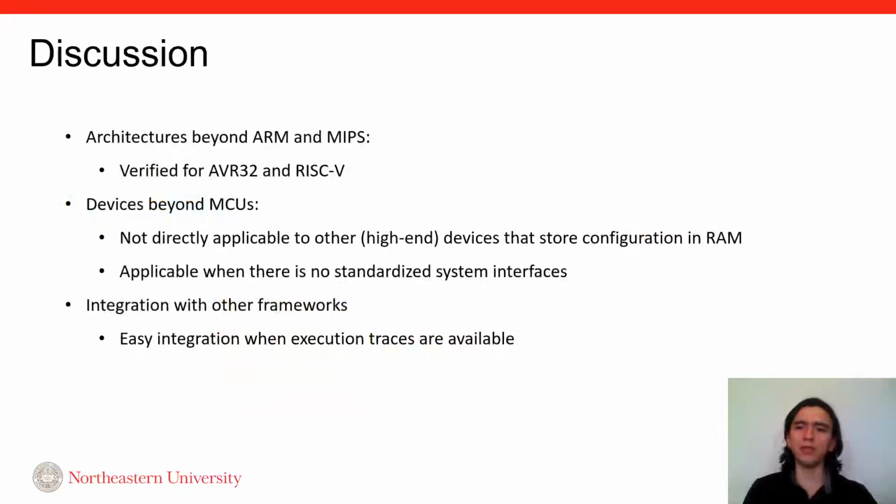We designed DICE to be generic. To work with other architectures, DICE needs 3 requirements. The first one is that the architecture designates specific areas for RAM, flash, and peripherals. Second, the firmware uses the peripheral area to store the DMA configuration using MMIO operations. And the third one is that the DMA transfer follows the DMA lifecycle that we described in this presentation.